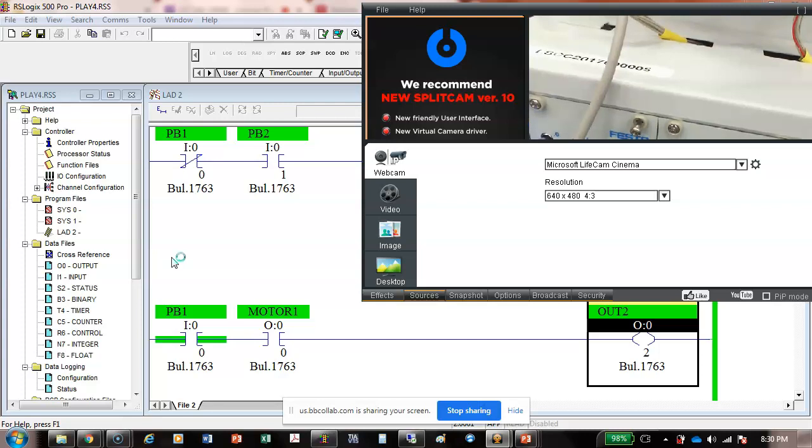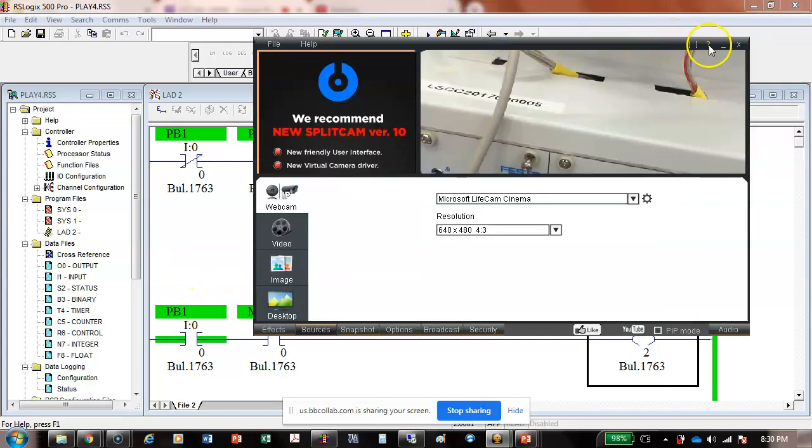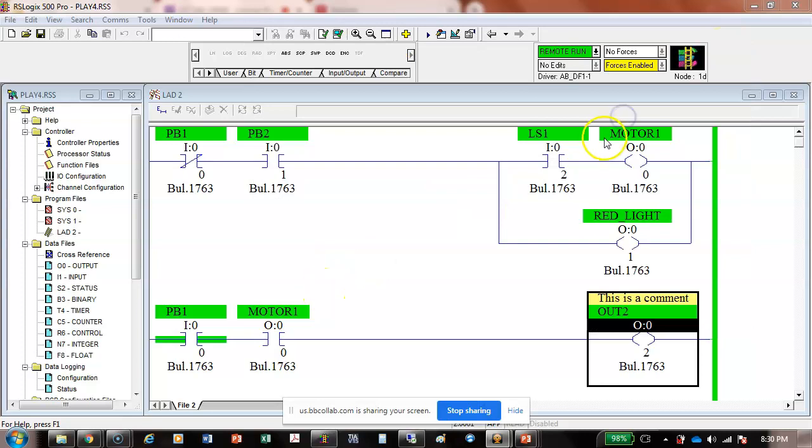But it looks wrong in motor controls. Because in motor controls, we wire up a normally closed push button. This is not motor controls. This is a program. When we deal with input ports, this right here comes from this right here, which comes from an internal coil. So that's a normally closed contact.